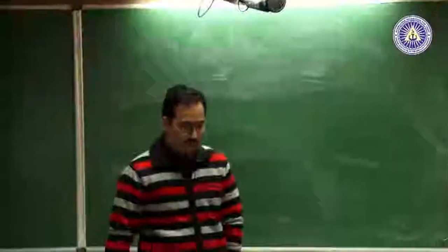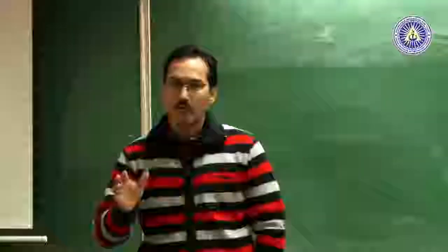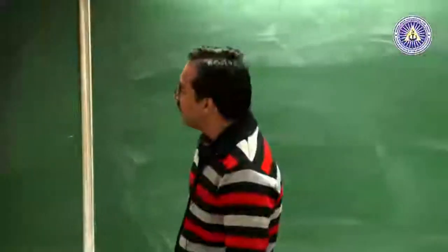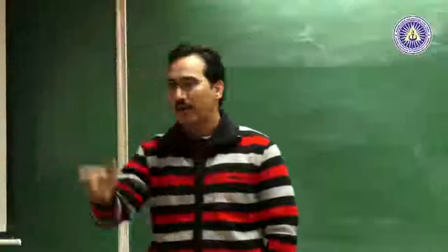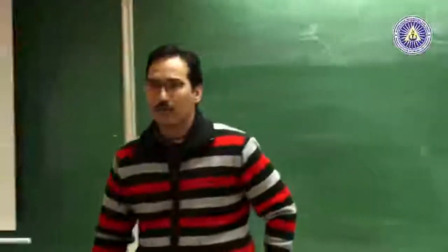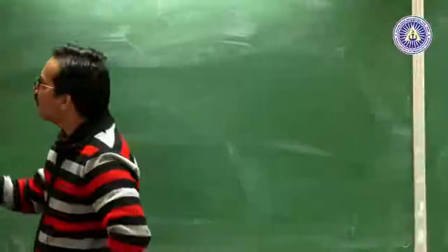We talked in particular about the static aspect, with one demo involving the so-called fluid aspect. Actually it involves both solid and fluid-like behavior, and we saw that the pressure in a granular bin saturates. We did a demo where somebody reasonably strong in our audience tried to push the sand and could not really bulge a balloon, which was supposedly a trivial task, and the reason is that the pressure saturates.